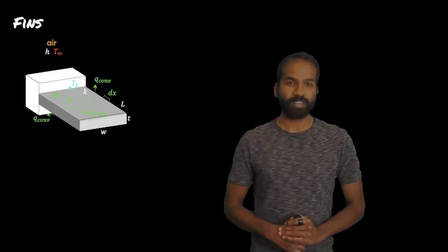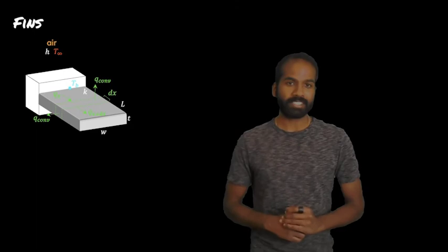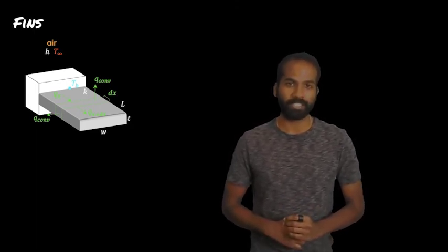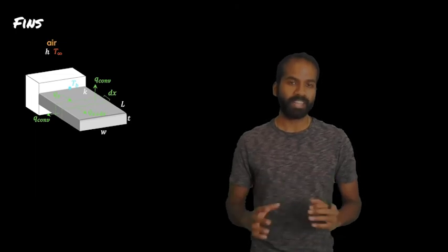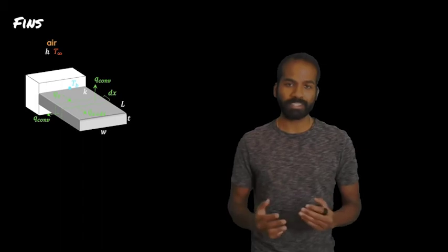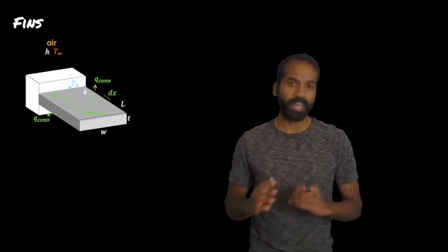Convection carries heat away from all faces of this fin. Even though a moment ago we discussed how most of the heat loss occurs from the face defined by L by W, there is a way of handling the heat loss by convection from all four faces of this differential volume, which can be done relatively simply. So we'll do that here.